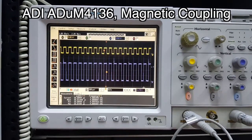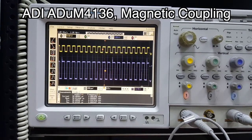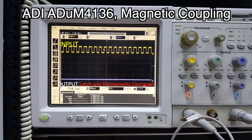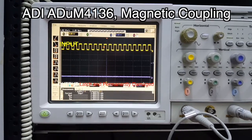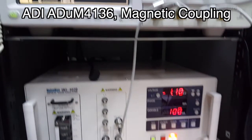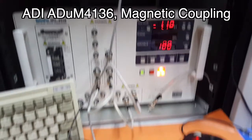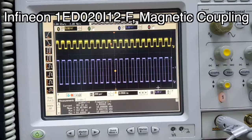The second gate driver we're going to test is Analog Devices ADuM4136, which uses chip-scale transformers to provide isolated communication across the galvanic isolation. It also has integrated DSAT detection to protect against short-circuit IGBT operation. The ADI gate driver output latches when negative 1100 volts periodic impulse noise is introduced on the surface of the gate driver's package. When latched, the driver is drawing excessive current and is permanently damaged.